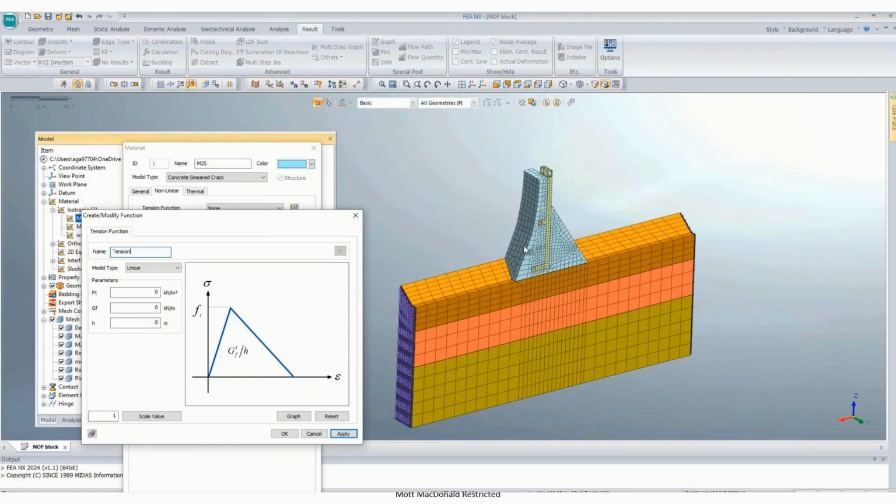That means that this dam is stable, that this is in equilibrium. Concrete has almost negligible tensile stress. It is because we don't get any node upstream of this, so some singularity would be there for these nodes to transfer the forces. So these nodes may have some tensile stress on the face, but you have to see how much tensile stress we have.